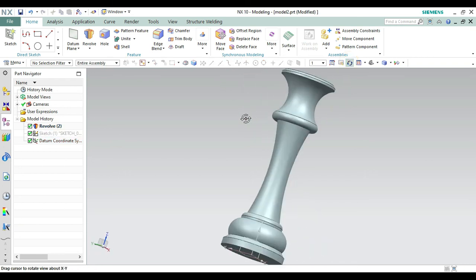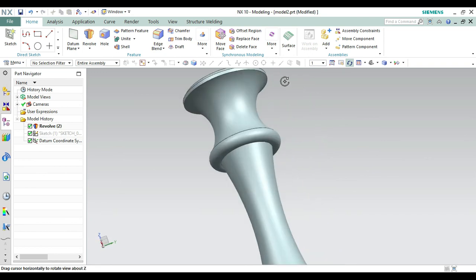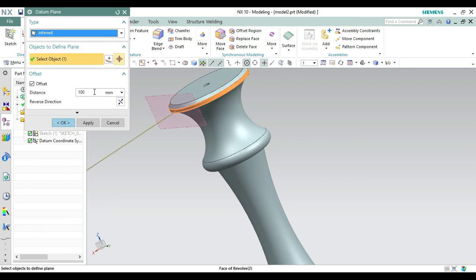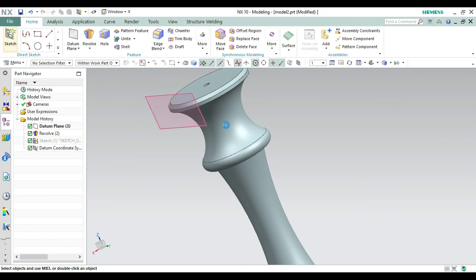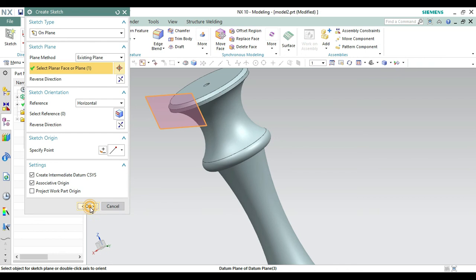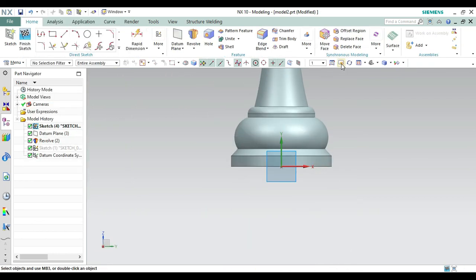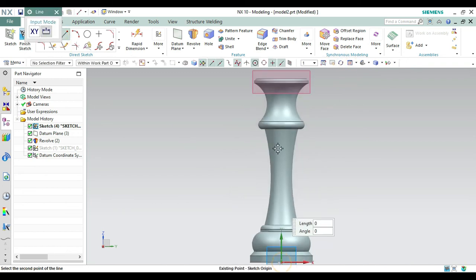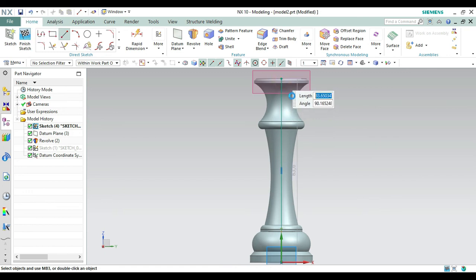Okay, now let's do this one and make it Control B. Let's rotate it. Okay, now what we have to do is first create a datum plane over this one. Okay, make the distance of 0 and make it okay from here like this one. Again going on the sketch, taking this point and like this one, let's make that fit. Again taking the line command, dragging it from here and touching the end point here. Nothing, we have to do the convert to reference.